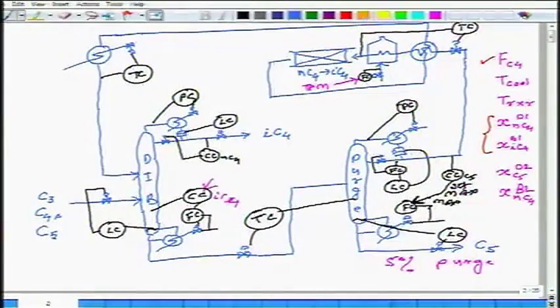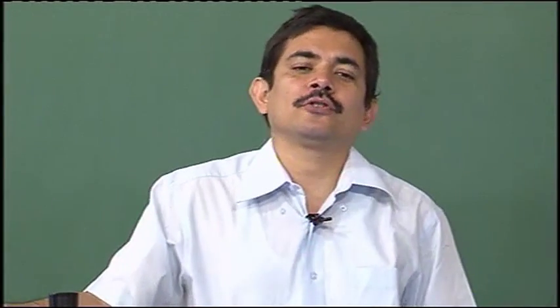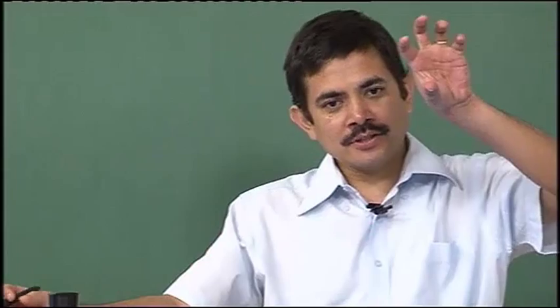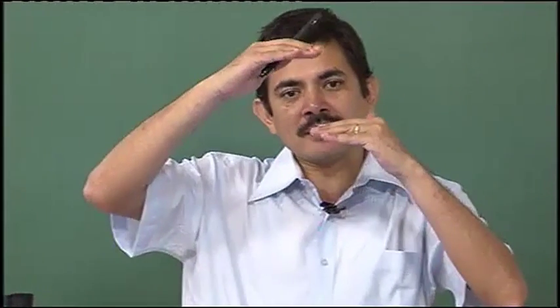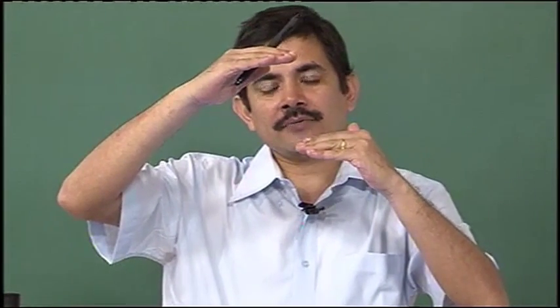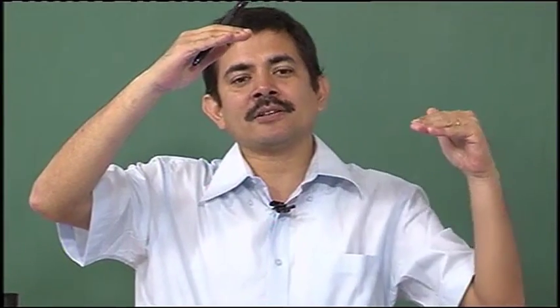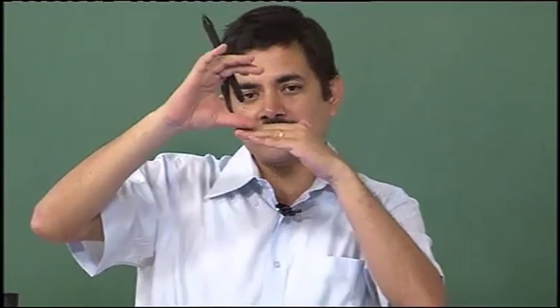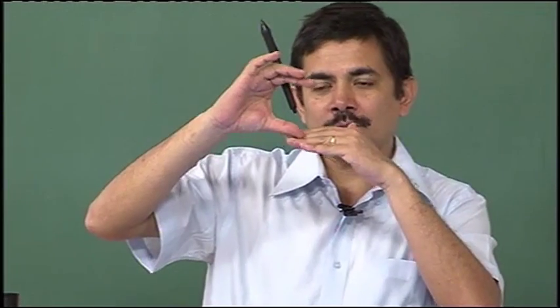So, but we didn't do it. Why did we not do it? Due to legacy? No, it's not due to legacy. It's because when you are trying to jack up throughput, furnace duty becomes active. If you are using it for control, then to control that temperature, you will always need some margin, right? So you cannot take the furnace duty to 100%. You will have to operate on average at say 90% furnace duty, so that 10% margin is there to keep the temperature in control.